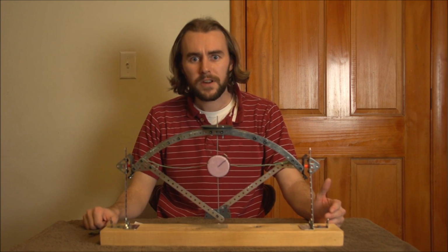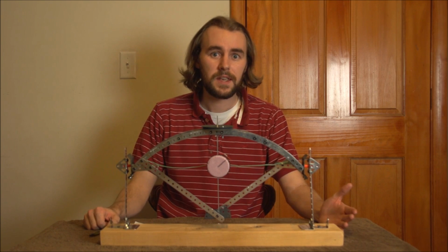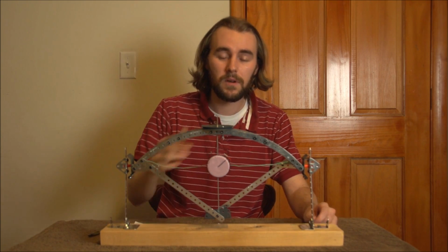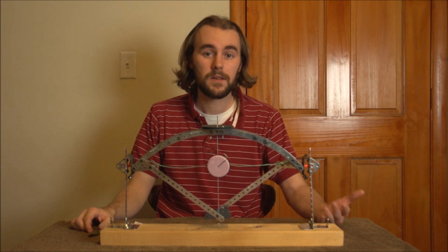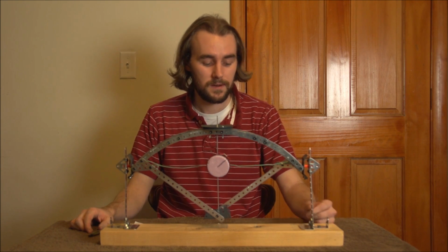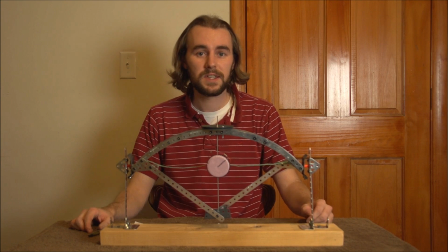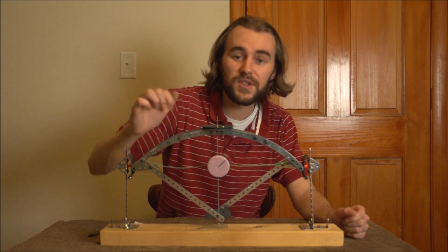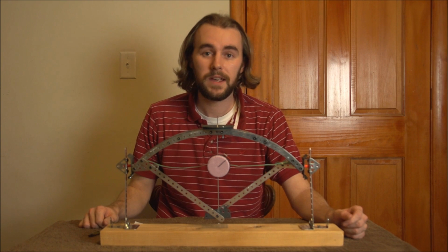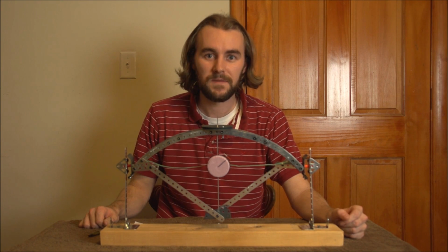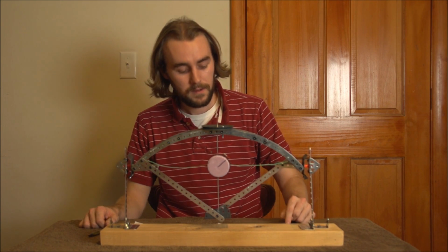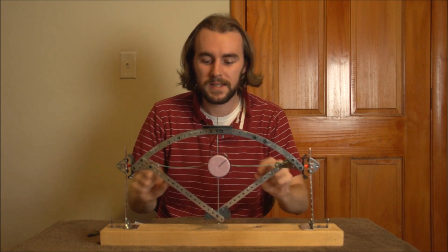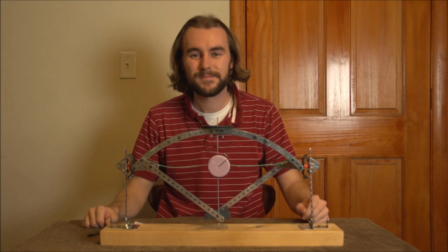So how does it work? Well, using equations learned in our flight dynamics class, one can calculate the actual yaw angle that it will go to when a pitch rate is induced. So the constants important in these equations are the moment of inertia of the propeller, modeled here as a disk, the angular velocity of the propeller, the pitch rate, and also the spring constants of these rubber bands here.